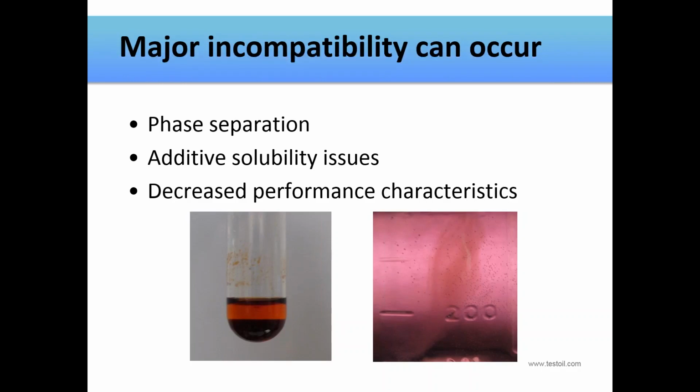So despite the potential visual major incompatibilities that can occur, the performance and physical properties of lubricants may decrease also, such as the ability to separate out water and air. We can have accelerated oxidation issues or even decreased rust and copper protection.